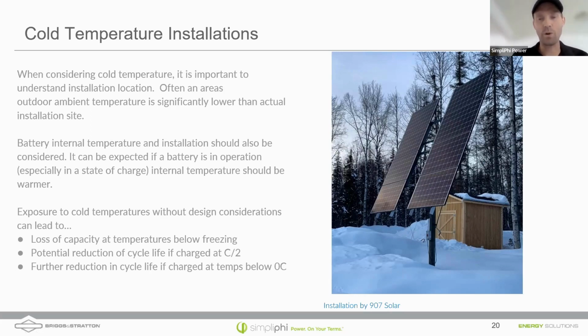But there are some notes on charging a battery in cold temperature conditions. There's a challenge for the lithium as it migrates to get into the anode side, which is typically graphite. Something like a syrup would get very slow moving and viscous at low temperatures, and the same thing happens inside a battery cell. At low temperatures, the lithium migrates much more slowly. So you have to be careful how quickly we charge and discharge a battery when temperatures get cold.